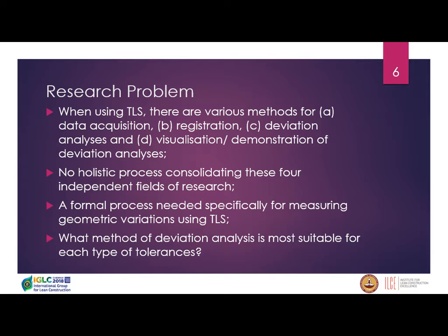You see, when we are talking about tolerances, we are talking about plus and minus 5 mil, plus and minus 10 mil, 2 mil, right? And all those areas, acquiring data, obtaining data, analyzing, have their own inaccuracy. So for instance, when you register data, your inaccuracy can be plus and minus 2 mil, but you are measuring a component that must be within plus and minus 5 mil. So you may be already 40% wrong. You may have like 40% error, right? So for us, it's very important to perform the deviation analysis to the highest level of accuracy.